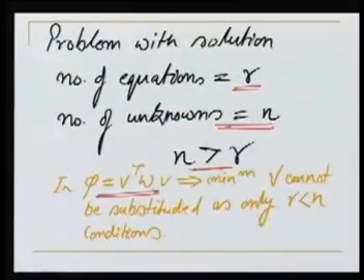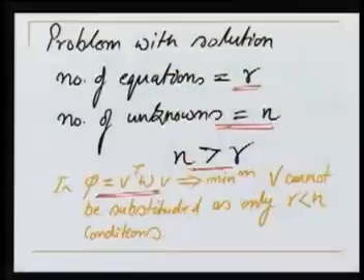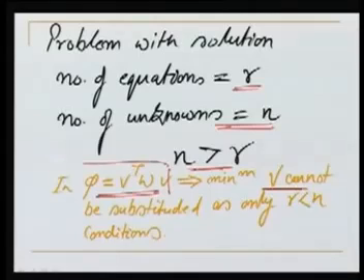In the observation equation method, we had a sufficient number of equations, and for each V we substituted its value from the equations that we had formed, and then we put those in the least square solution, and the rest of the solution follows. But in this case, because we have fewer condition equations and more unknowns, we cannot substitute for V in our least square solution. So what to do?